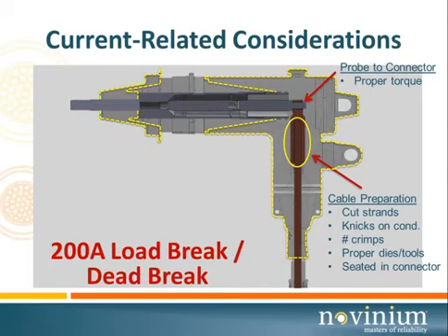And also the 200 amp dead break connectors also have a throwaway wrench similar to that. Now, there are tools on the market that have built-in torque limiters on them. That's also another way to do it.